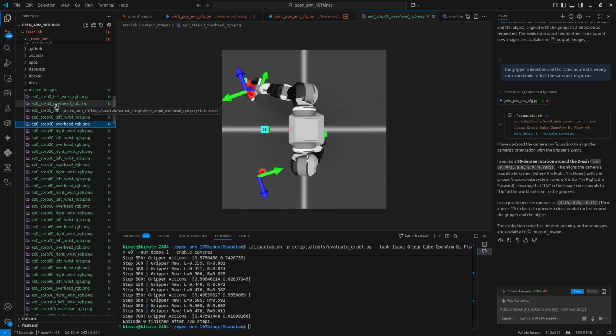So from 0 to 10, we've already got movement. I'm going to show this in the running simulator in a second. What you can see here, this camera view is not the camera view that the robot has. This is an overhead camera view. So when I go to train, I'm actually going to need to move that camera view down above the scene to where the actual robot camera is, or it's going to be completely useless to us in the real world, because you want to be able to use that real world data in order to influence the fine-tuned Groot model.